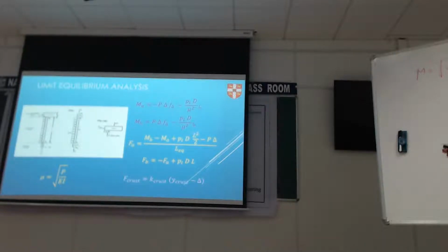Using those two, if I know the moments, I can write the force equations. By the way, you can check these if you want. Now LEQ I'm taking as the length of this pile, but if you want, you can adjust that using your engineering sense. If you feel that the pile is going to bend more if it's not quite rock socketed here, or if you got more length into dense sand, you can adjust the effective length. We kind of looked at that before, how to work out effective lengths of a pile and flexibility of pile are covered separately. But you can use that.